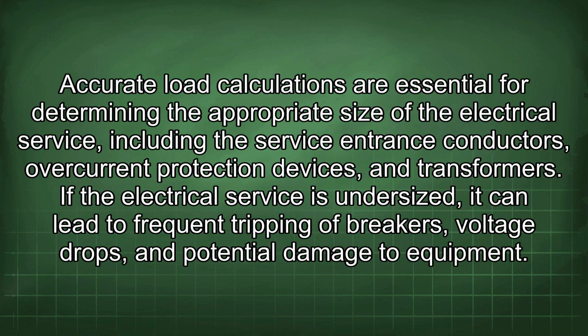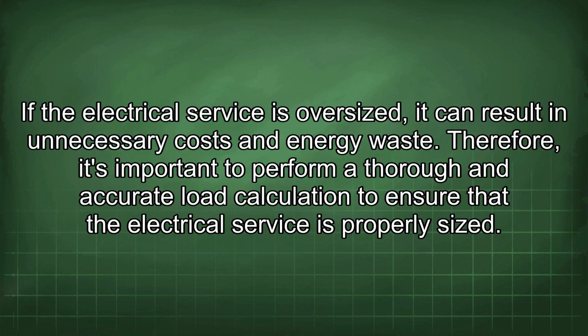Accurate load calculations are essential for determining the appropriate size of the electrical service, including the service entrance conductors, overcurrent protection devices, and transformers. If the electrical service is undersized, it can lead to frequent tripping of breakers, voltage drops, and potential damage to equipment. If the electrical service is oversized, it can result in unnecessary costs and energy waste. Therefore, it's important to perform a thorough and accurate load calculation to ensure that the electrical service is properly sized.